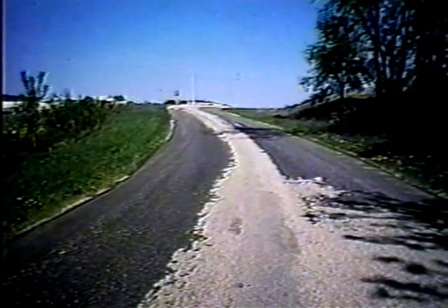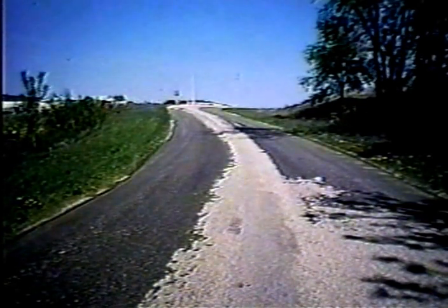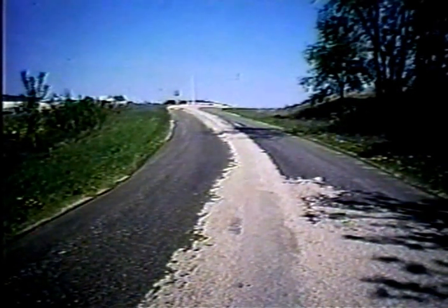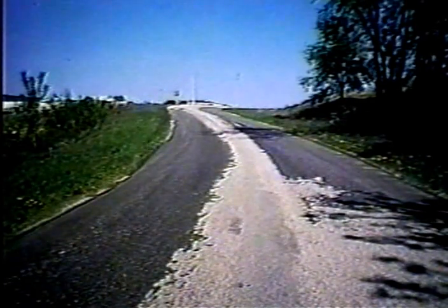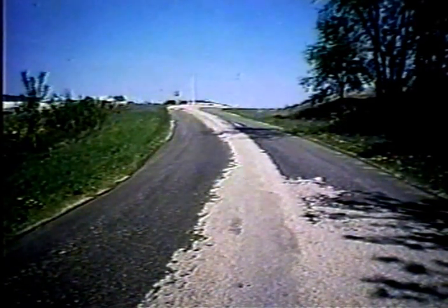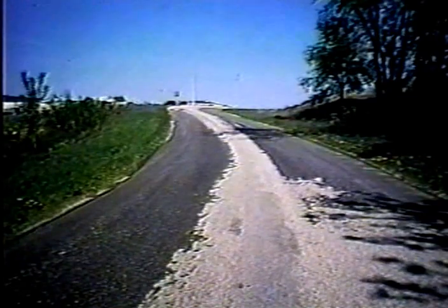Here we have a wedge that has been placed on the outside edge of the pavement. This is a common maintenance practice where you have more distress accumulating. They'll lay in an asphalt wedge to provide some additional strengthening and to kind of restore the shape and the crown of the roadway. What I like to do is put a wedge down like this, or even make other permanent pavement repairs, and then watch their performance with time. If a repair like this lasts for a year or two with no significant distress, to me that says we have restored the pavement, and perhaps you can move then to a surface treatment, like a seal coat.